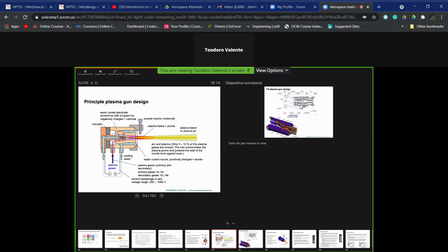And then I will be back. We have the nozzle, here designed, for example, as the de Laval nozzle. So we have the plasma, which is formed. We have the recombination area. We have the particle injection, the powder injection, which is essentially external. And so particles, when the parameters are well selected, experience this kind of trajectory, for example. And so they can be melted and they can be accelerated. They can be projected here where there is the substrate to be coated.